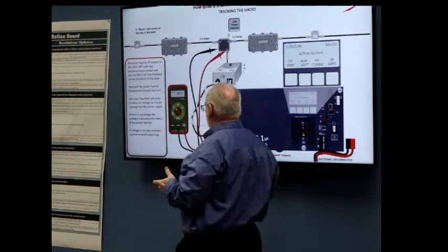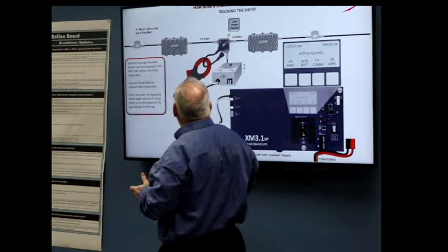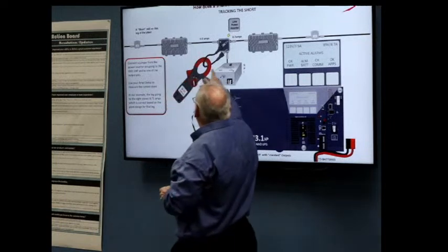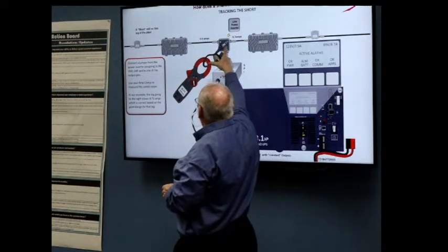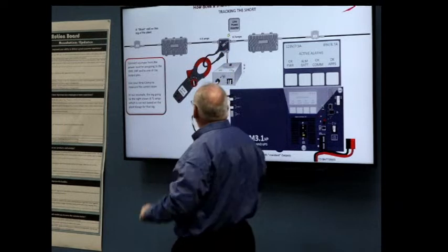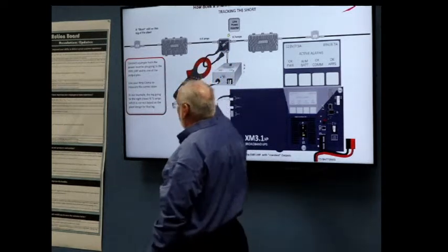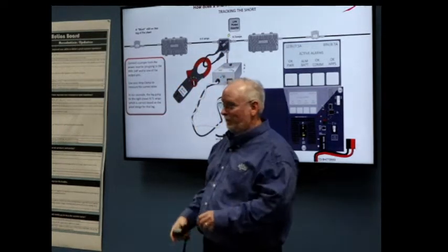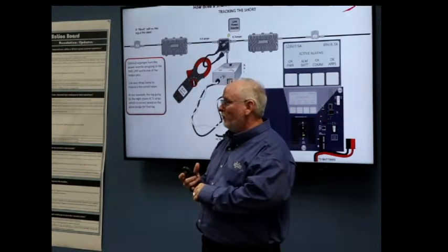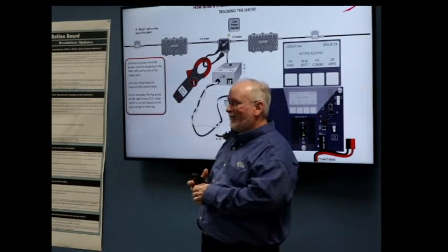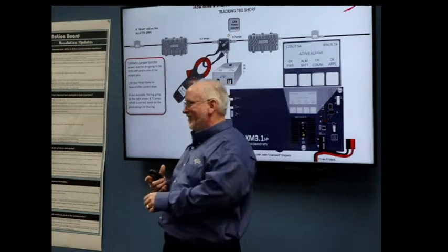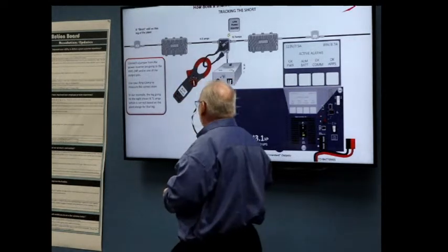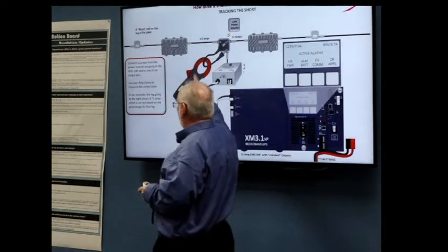Okay, looks good. Then test the current. Using a jumper, there'll be little tabs here that you connect a jumper wire to. This jumper wire needs to be at least a 12 gauge wire, by the way. Okay? Well, yeah, use a 24 gauge wire. It's going to end differently than what you want in this test, right? Use 12 gauge wire. Use a current meter, right?